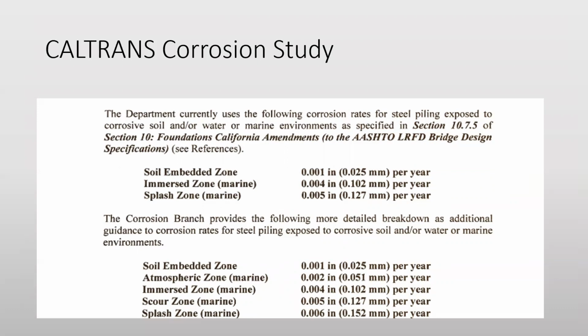The department cited that sacrificial metal be incorporated into the design of the pipe wall thickness to compensate for the loss of metal that occurs due to corrosion. This extra metal thickness is added to all surfaces of the pipe that interact with the soil and water.